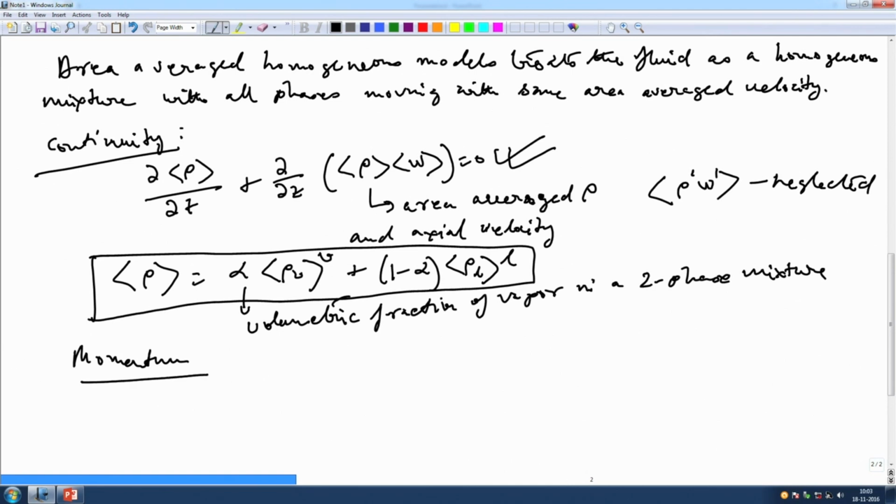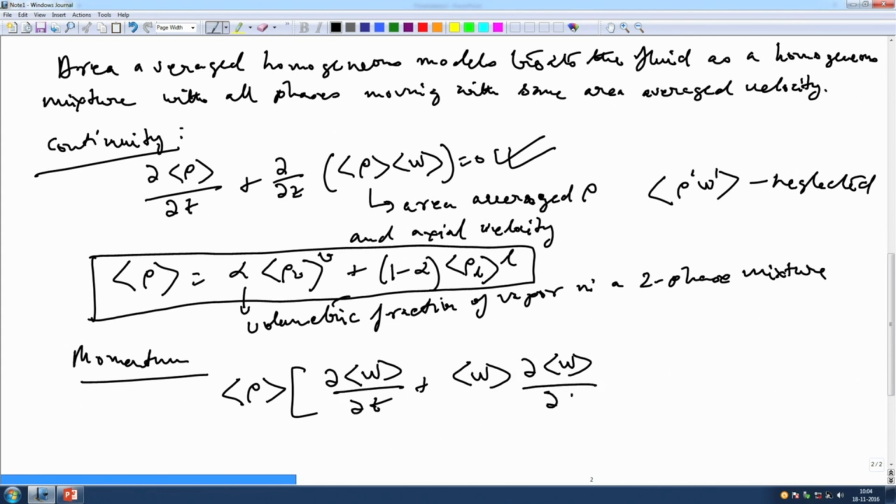In the case of momentum, this becomes much easier because we are dealing with only one dimension, the other dimensions are not there because of this. If you know your pipe flow and other equations like this, it should become very apparent why it should look like this. But of course, the pipe flow does not retain the convective term. But in the entrance length where the flow is developing, these terms will be there.